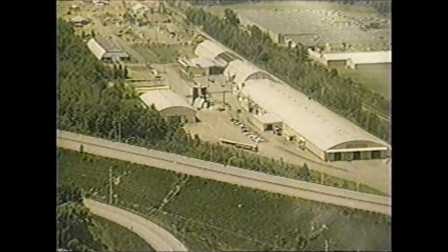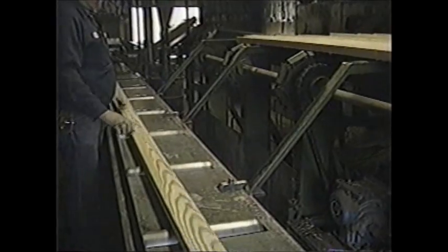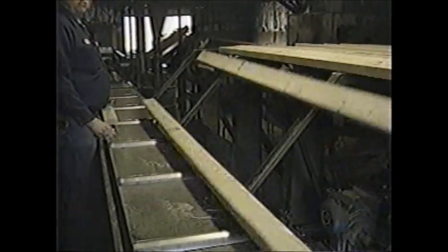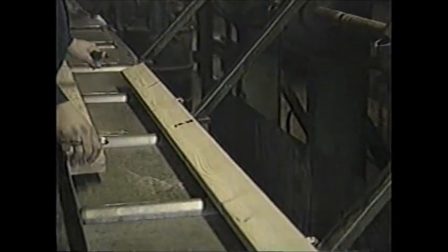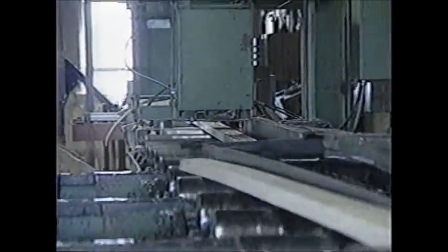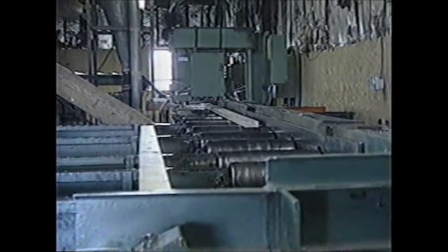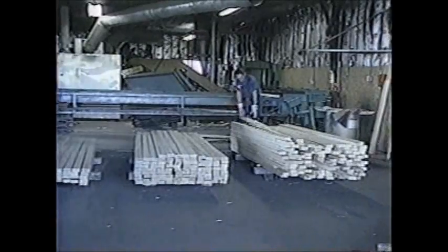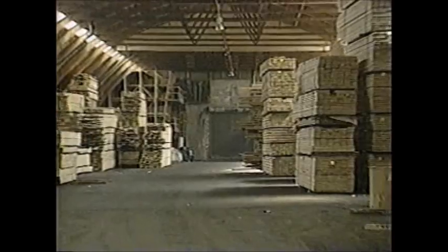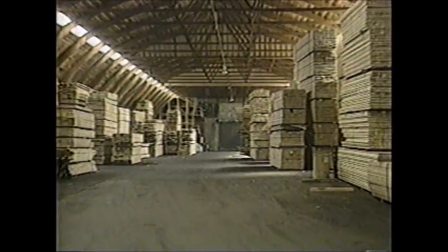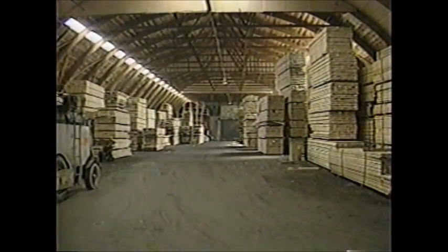The last plant we'll visit on our tour is the Unilam division of Unadilla Silo, located in Unadilla, New York, manufacturers of glued laminated beams and timbers. Incoming southern pine is carefully graded according to standards required in the production of glued laminated beams and marked for trimming. The graded lumber is trimmed automatically and is then piled according to the grade mark on each piece. The plant maintains an inventory of graded 1- and 2-inch lumber in several widths.